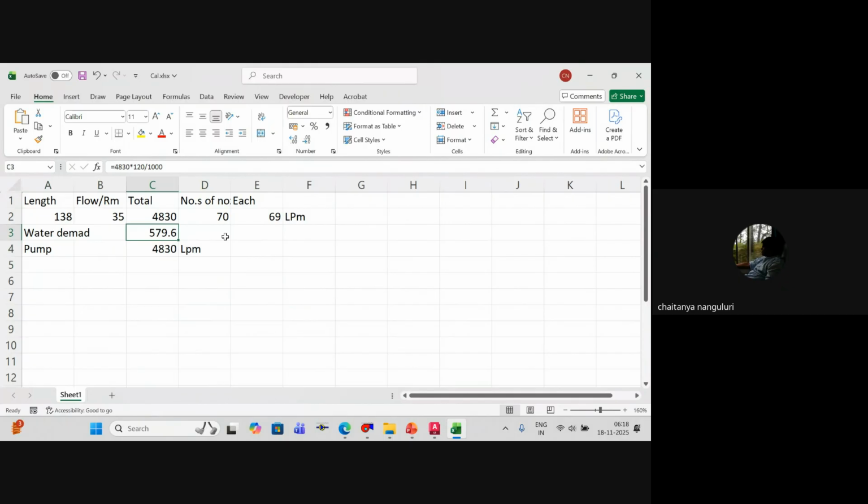And for this, you have a separate pumping station. That means you will not combine it with your hydrant sprinkler, and you can't use your existing hydrant or sprinkler system for your water curtain. This water curtain system is entirely an isolated system. So, though your tank is common, you will take from a common header or a separate header you will create for this, and then you have to have a separate pump station from which you will connect to this entire water curtain system. Understood or not?